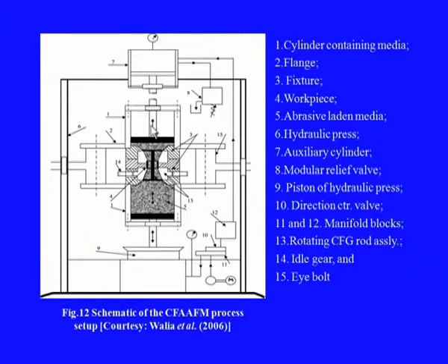This is kept on rotating with some devices, with gear devices, which is connected through this tooling arrangement, and the speed of this rod can be adjusted according to the requirement. Now, because of the introduction of this rod, the pressure inside will be enhanced, the restriction will be more, and therefore, the effect of these particles on the finishing of these workpieces will be much more.